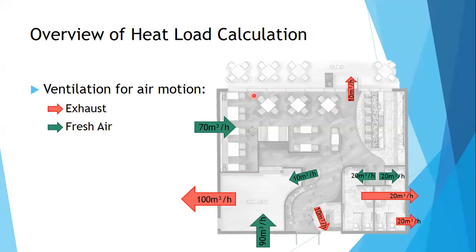All right. This dining area, I put a fan here. If I put a fan going in, it is a positive area, or positive ventilation, because I'm introducing outdoor air to this space. So this space becomes positive. If this is positive and this is negative, the air from here naturally goes here.